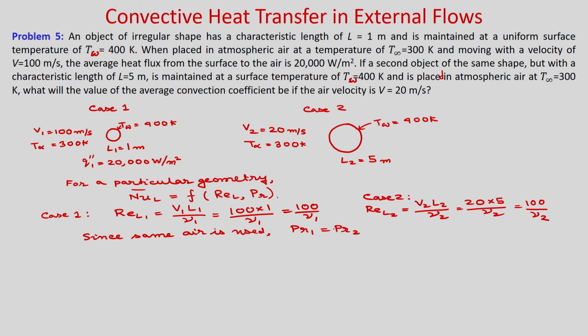Similarly, for the same air your kinematic viscosity will be the same, so nu 1 is equal to nu 2. So, you can write Reynolds number for L1 will be equal to Reynolds number for L2 from this expression.